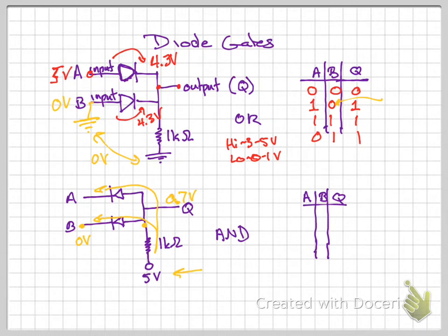So there's one other thing that maybe when you start thinking about these gates you start wondering: what about the output? Doesn't the output change what the gate does? Yes, the output does. That's why, as we studied in a very early lab, the output ideally has an infinite resistance. So the output pulls ideally no current from the circuit. Because if the output was just shorted, then that would screw everything up here. That wouldn't allow these gates to work. So the output has an infinite impedance, or a high impedance compared to the circuit, so it pulls no current, so we don't have to worry about current flowing to the output. So we don't have to worry about what the output's doing to the circuit.